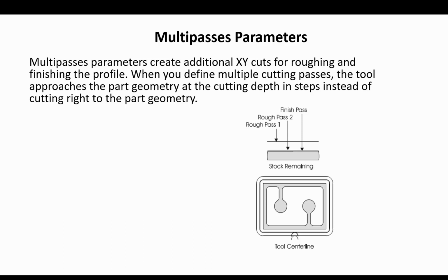Hi everyone, in this video I'm going to explain the multipasses parameters that are part of the contour toolpath. Multipasses parameters create additional XY cuts for roughing and finishing the profile.